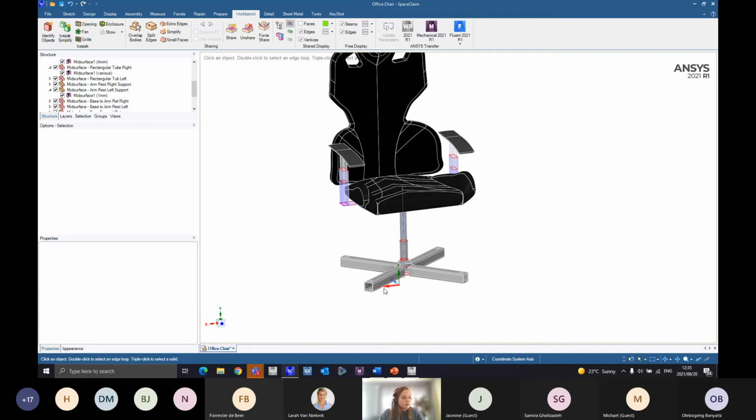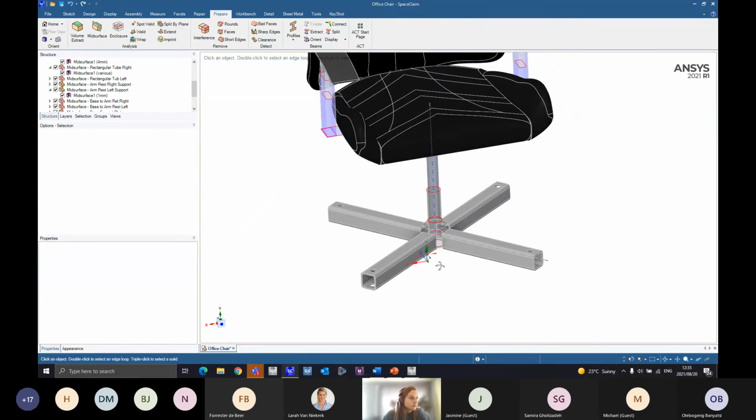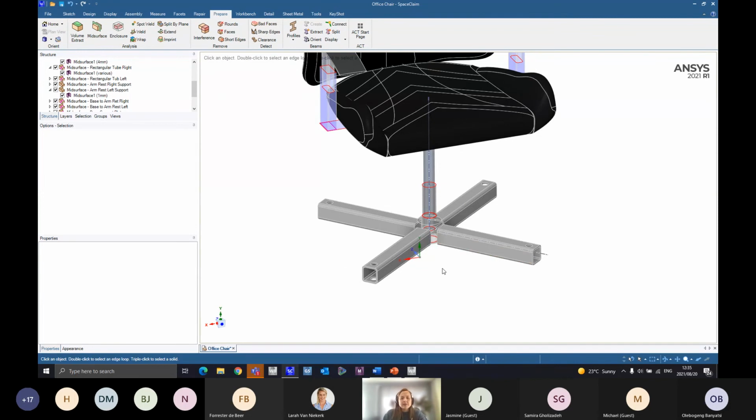of water quickly. So one of the coolest features that I really enjoy using is when you work with structures and you have a lot of beams or channels and things like that, and you can't really model all of these beams with 3D elements. It's not feasible at all. Then you can use your beam elements. So the only thing that it requires is a constant cross-sectional area. So anything that has a constant cross-sectional area, you can actually extract a beam profile.